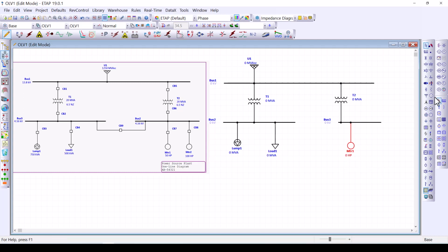And instead of clicking here to add the second load, let's say I want to copy this component. We can do that in numerous ways, one of which I want to show you right now is to press Control and Shift together, click on the component, and you would see the drag and drop methods. So just drag and drop, then connect that. Finally, we need to just work with this cross tie and add all the breakers.